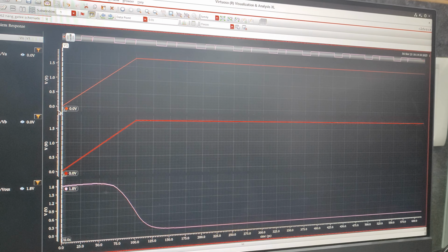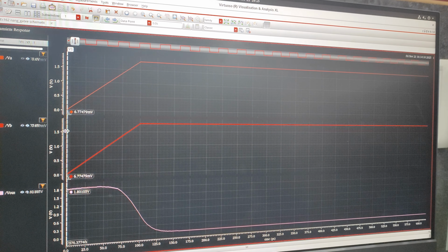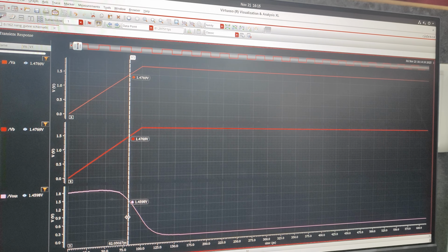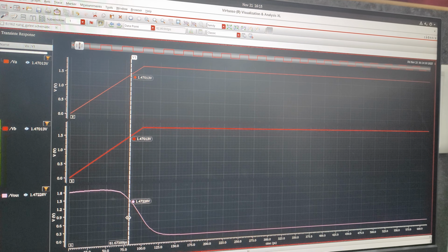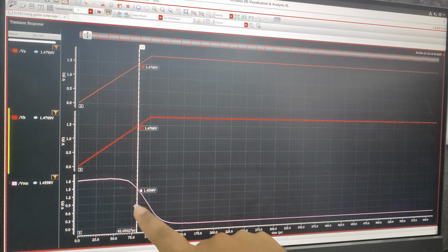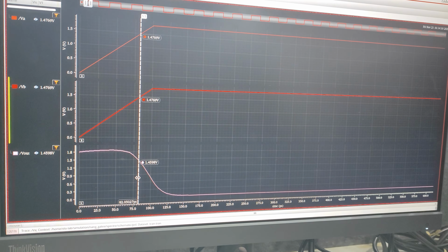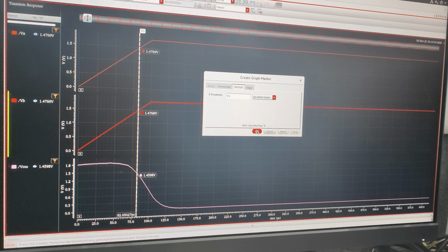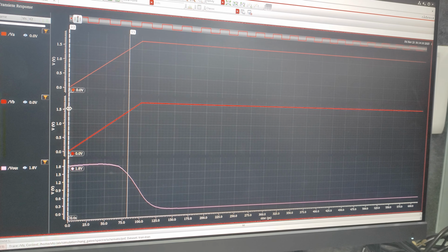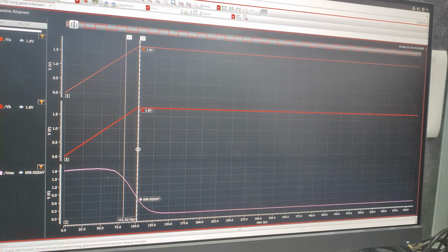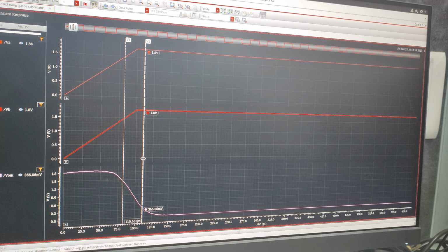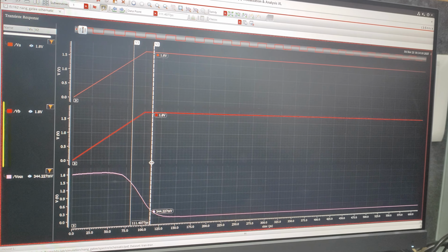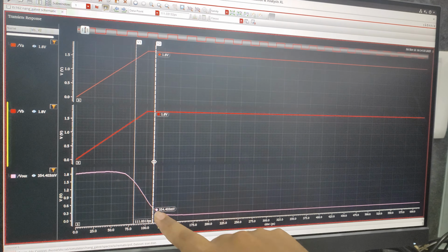Since we set 1.8 volt, one value should be at 1.44 volt. So see, I came around 1.45, 1.43 as an approximation. This one, V out, okay, this is 1.45. Then take one more marker, create marker, click on OK, come to 0.36, okay, 0.36 is 20% and 1.44 is 80% value. So somewhere around over here, 3.54 I just came as an approximation.